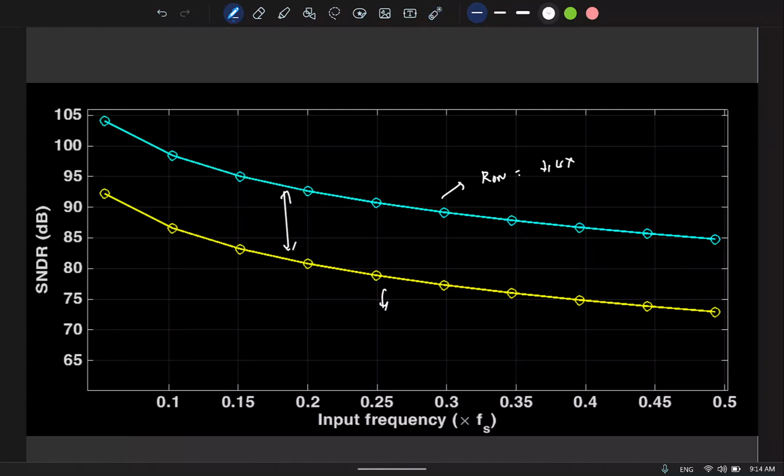And remember that for any MOS switch, the on resistance, how is it related to the W by L? It's inversely proportional to W by L. For any switch, we already saw that we have to choose the length to be the minimum length. So if you have to reduce the on resistance, what should you do? I have to increase the width to reduce R on, right? And the bottom line, we have to keep this term much smaller than 1, right?